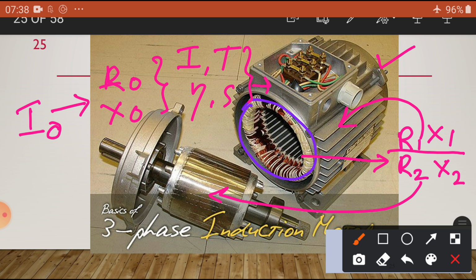That is why the induction motor has a circle diagram, which tells its performance values at any given load. To draw the circle diagram, we require these components. How are we going to get them? The manufacturer itself will measure them and print them on nameplates or in booklets.